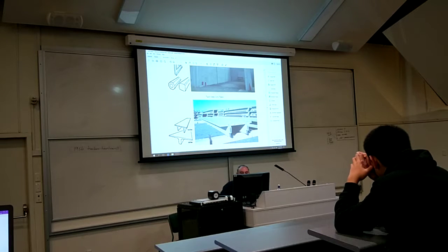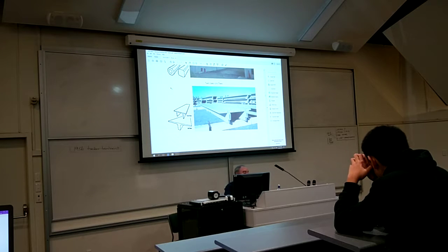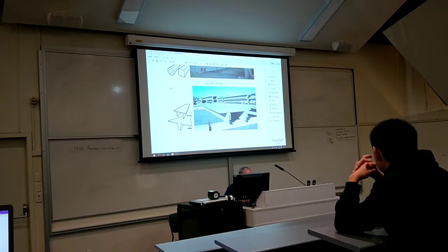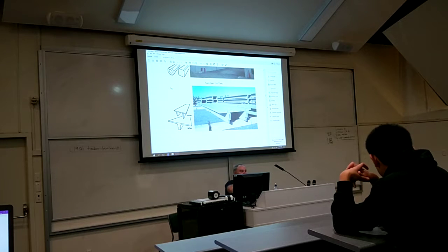Uni-Ts, twin Ts and Uni-Ts. An example of these would be Mount Albert Palisade. If you drive under there, look up, you'll see Uni-Ts and also twin Ts. We had a problem there when we were designing that, and that was to do with the height. We didn't realise the bedrock or the lava flow from Mount Albert had gone all the way down through that area. And so every time we took like 100 mils, we had to dynamite the whole lot even further, and it was costing more and more money until someone came up with the idea of using twin Ts, which meant that we had more room underneath than the Uni-Ts for cars to drive underneath. So we saved ourselves quite a bit of money by using twin Ts.